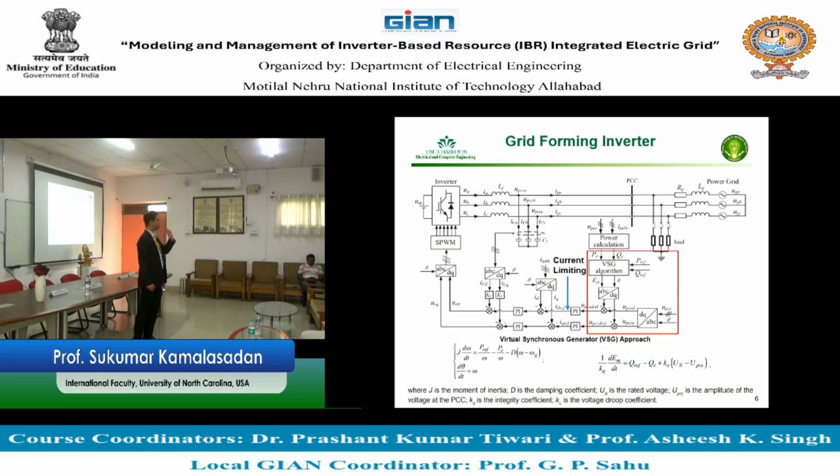So fundamentally, in a forming architecture, you will need this angle and you will need this voltage because you don't have an electric grid connected. So at this point of the inverter, we should have a voltage and we should have an angle made by the inverter itself. Such inverters are called forming.